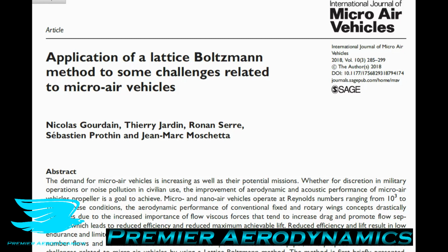So that means that you have a limitation on how many cores you can use to solve your equation, which means that you can only really speed up your CFD simulations so much. That's where the Lattice Boltzmann method comes into it. This is the major selling point of the LBM CFD approach, and that is that it scales far more linearly.